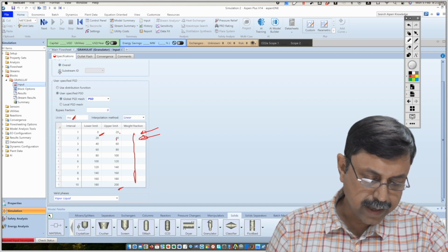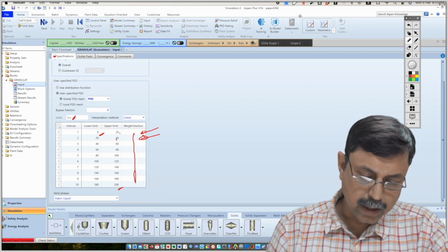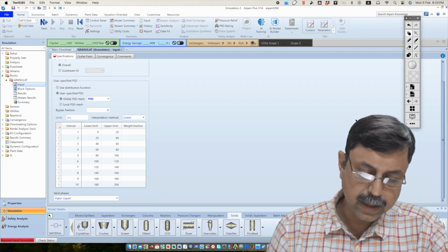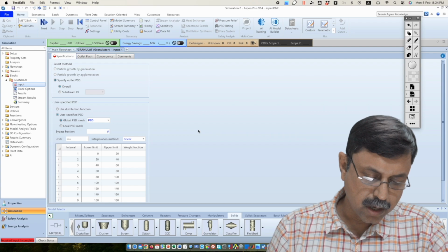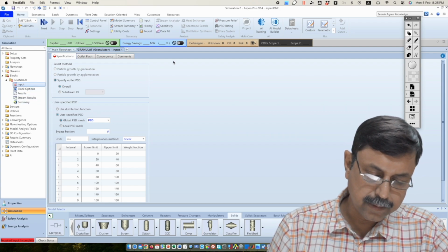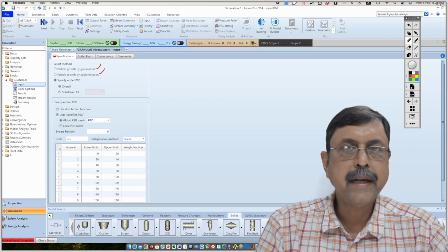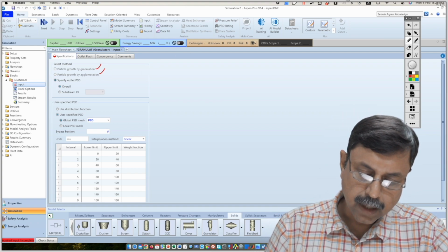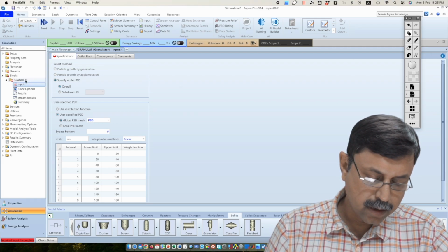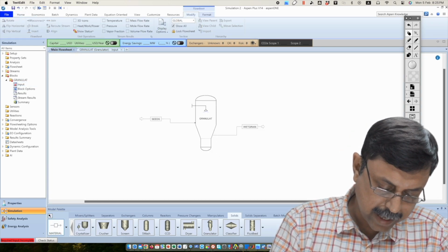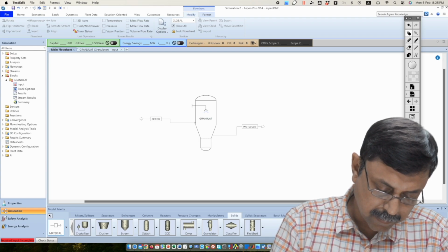Right? But as I said, by doing so, you will not be able to do any calculation on the basis of granulation or agglomeration. So for getting these two options open for you, you need to supply the binder material. Okay? So let us add one more line in the flowsheet, that is for the binder material. So we add another material stream over here.